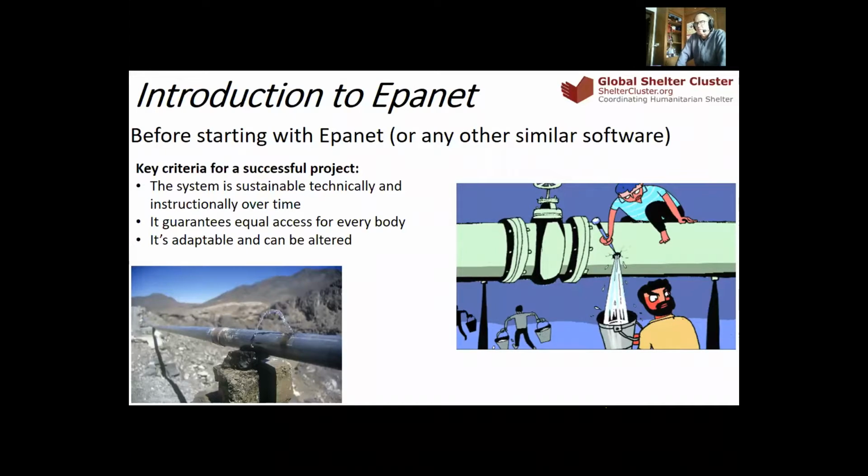If you don't give access to all the people, you will have the situation in the picture on the right, where you will have many illegal connections. And additionally, if you do a new network, you have to plan in advance about the development of your sites. If you size your network for 1,000 people, you have to calculate that the network will last for 20, even more years, and the population might increase accordingly. Therefore, you should size your network considering the development of the area.